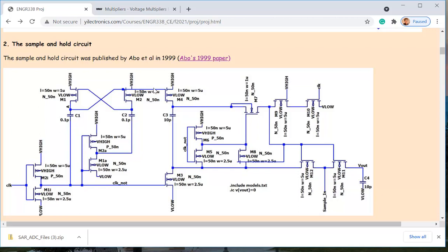If you only have a VDD, your VGS is going to be 0, right? If I have a VDD here and you pass VDD here, then VGS becomes 0. So which means you can never pass the VDD from here to here if you only turn it on at VDD. So the voltage here will be VDD minus VTHN as the largest. So you want to turn on this more.